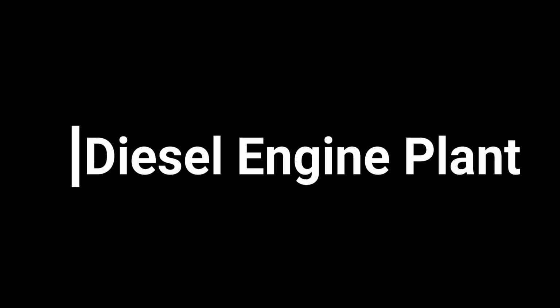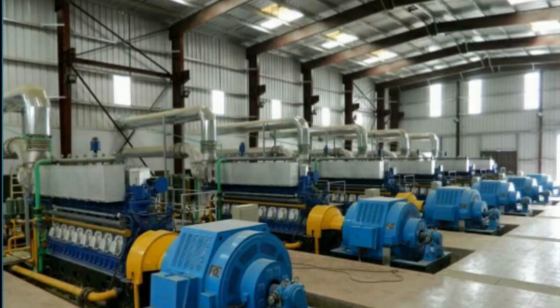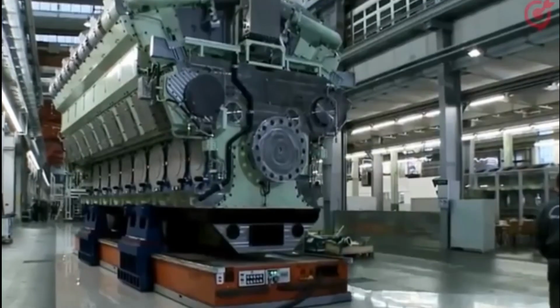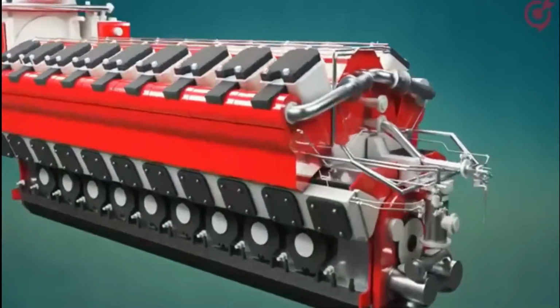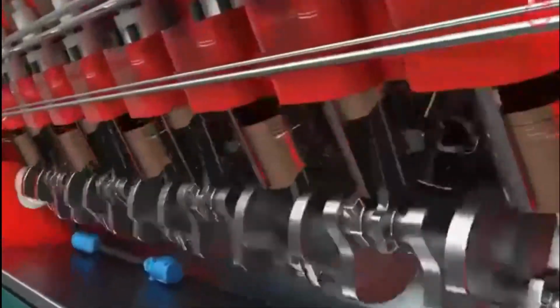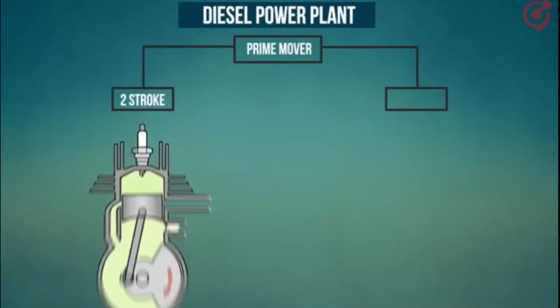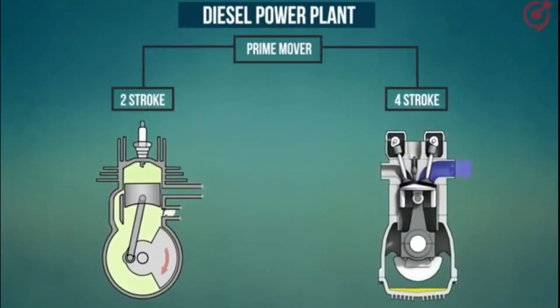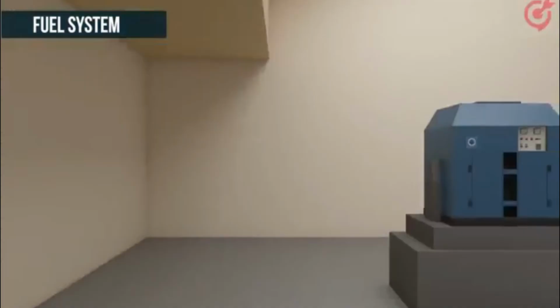Diesel engine plants are usually built for remote communities and ships. The plants usually operate as baseload generation, 24 hours a day to supply power to industrial facilities, the camp, or villages. The engines for baseload are of slow speed, 400 to 900 RPM type, operated on continuous duty.